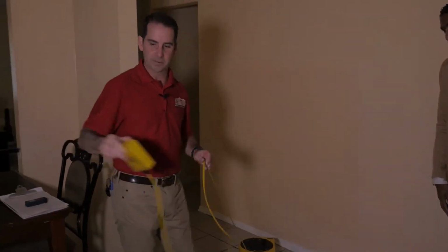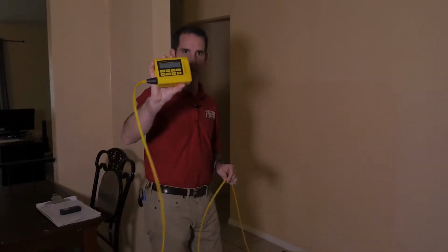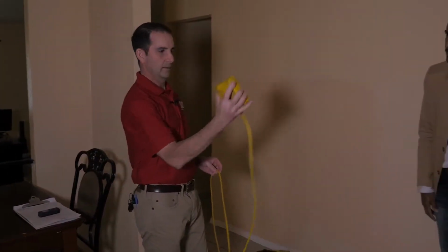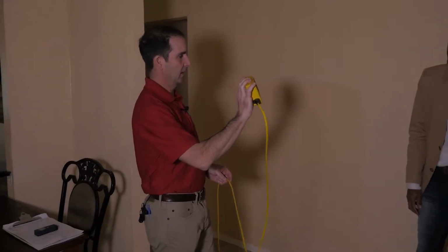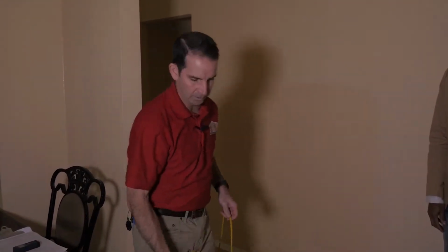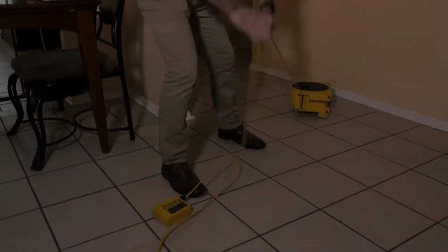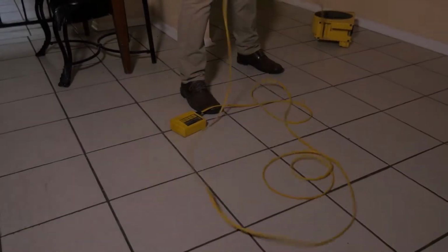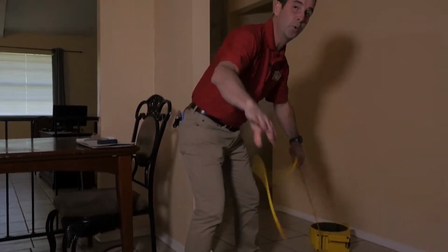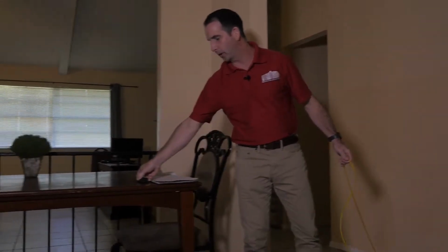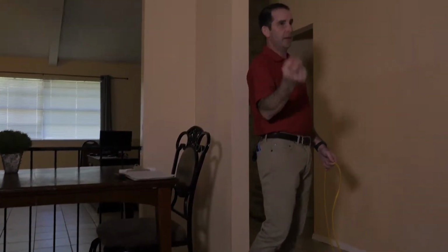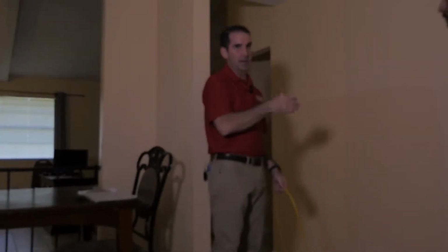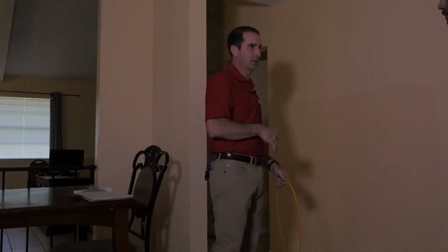And so this meter that I'm gonna show you here is gonna tell us how high or low the slab is. Okay, this is gonna register our measurement. What I do is I unfurl the line here, and I'm gonna pick a point. Remember, I've drawn a diagram of the house to scale on the outside. I've marked all my exterior stress signs, and now I'm ready to take the elevation survey.